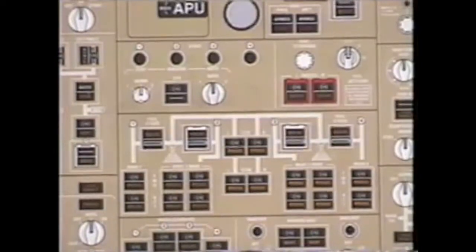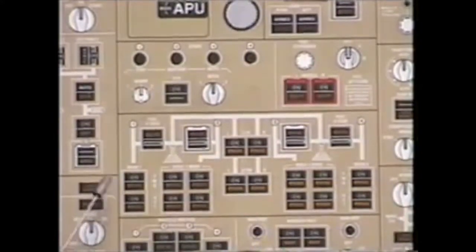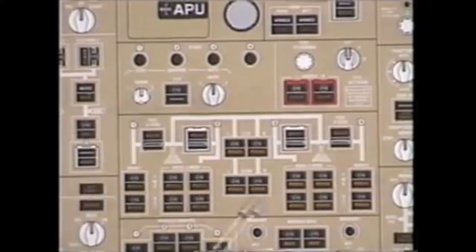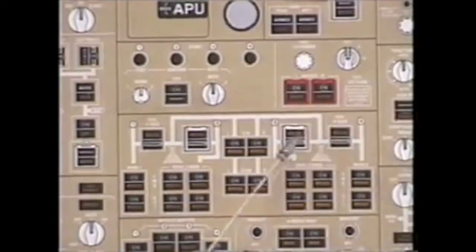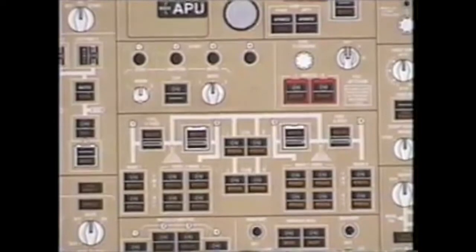There are 8 fuel tanks on your airplane: main tanks 1, 2, 3, and 4, and 2 reserve tanks 2 and 3, which are physically outboard of your outboard main tanks. There's a very large center tank and a stabilizer tank. Of those 8 tanks, the only 4 tanks you can actually take the fuel out of and pump it directly overboard are the inboard mains, the center, and the stab.